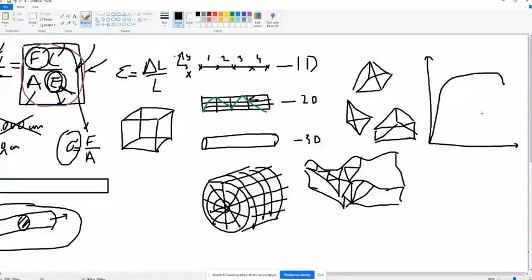From this perspective, when you are using a load cell for measuring the force, you need to know the sample. What will be the reaction force around? You can say that the values may be 400 kilonewtons or 500 kilonewtons. So you need to select a load cell between those values. You need to know the range.